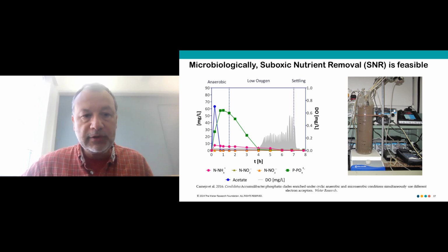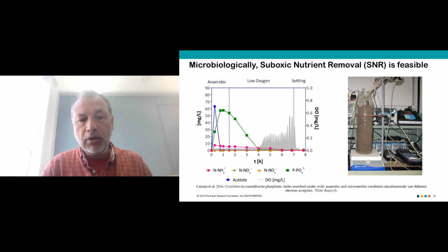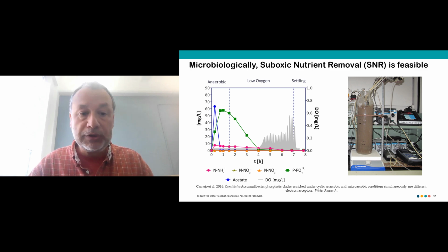And then you see complete removal of the phosphorus. You see nitrification. You see no accumulation of nitrite or nitrate. And then when all the organic is consumed, this threshold of 0.2 milligrams per liter of oxygen starts taking place. We had an on-off switch, so the oxygen fluctuates around 0.2. When all the ammonia is exhausted and there is no more oxygen demand, that's when we started seeing more oxygen. So this is an example of complete nitrification, complete denitrification, complete phosphorus removal, maintaining oxygen at less than 0.2 in general on the overall thing. So we have known that in the lab for a long time.